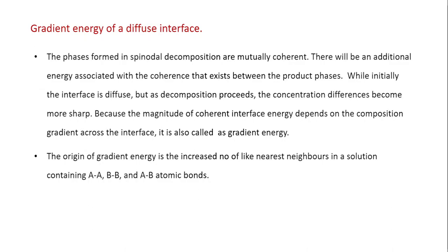Because the magnitude of coherent interface energy depends on the composition gradient across the interface, it is called gradient energy. The origin of gradient energy is the increased number of like nearest neighbors in a solution containing AA, BB, and AB types of bonds.